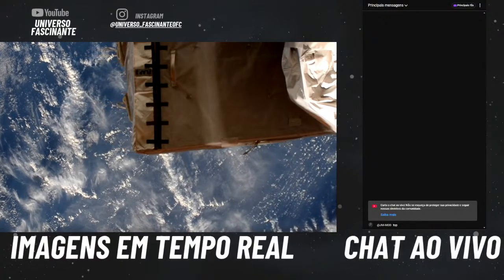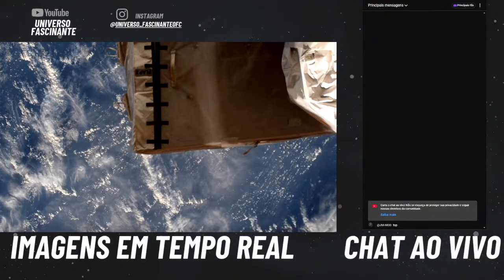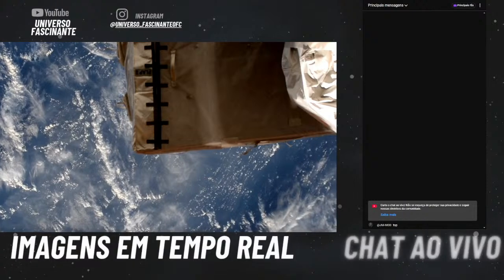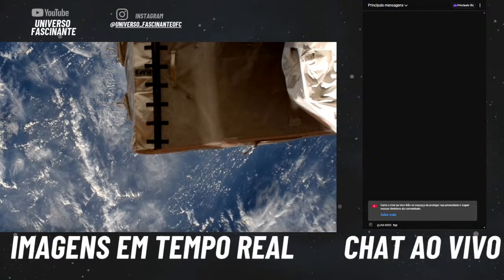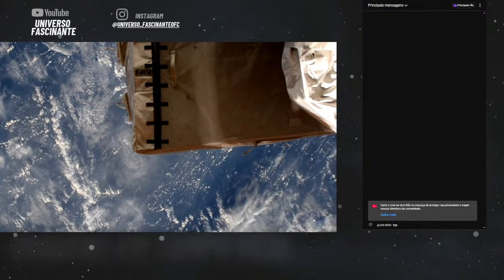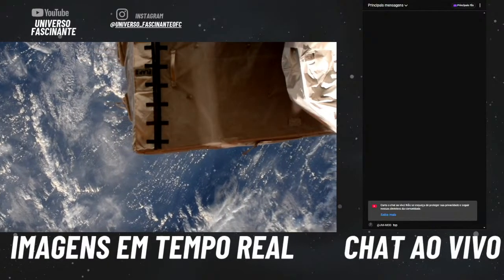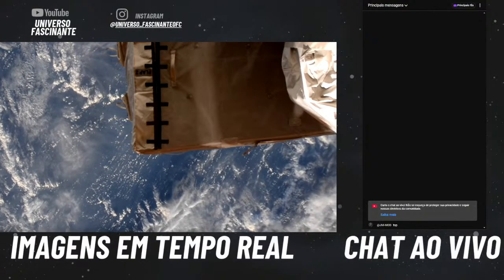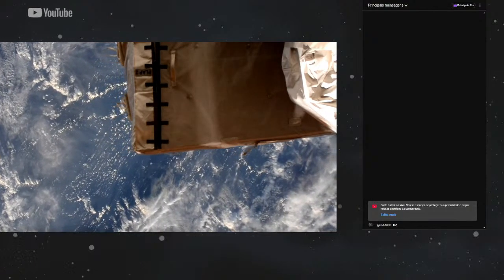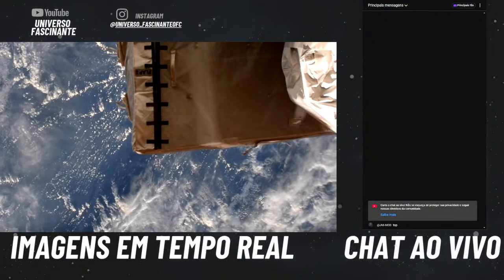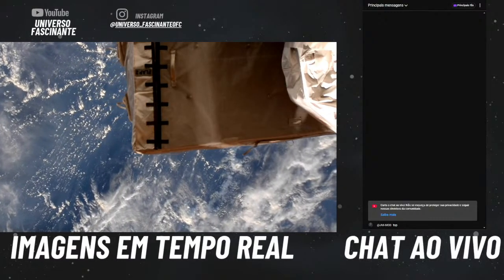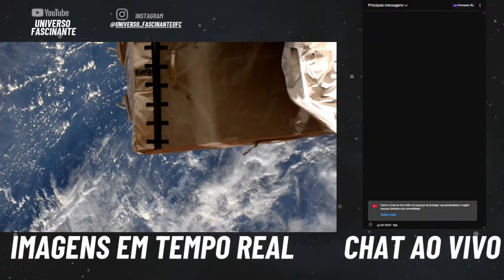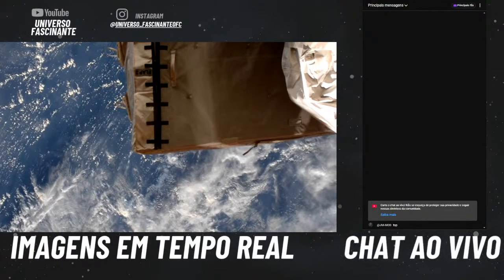We are 30 minutes away from the deorbit burn. This is an animation that shows the activities of the 4-minute, 42-second retrograde firing to enable the Soyuz to drop out of orbit. About 24 minutes after the deorbit burn is complete, the separation of the modules pyrotechnically will discard the instrumentation and propulsion module and the orbital module, leaving only the descent module flying in the direction of travel toward the landing site with its heat shield repelling temperatures building up to about 2,500 degrees Fahrenheit.